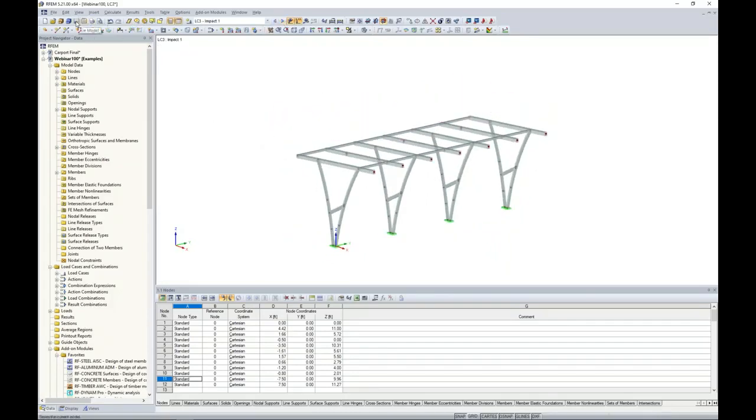Now for impact load, this comes from the ASCE 7 2016 and specifically section 4.5.3 for vehicle barrier systems. The code tells us that for impact loads, we should consider a 6 kip load applied anywhere between 1 foot 4 inches to 2 feet 3 inches above the floor. So for this application, I want to consider an impact load on my center columns here.